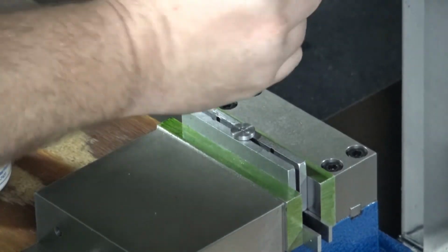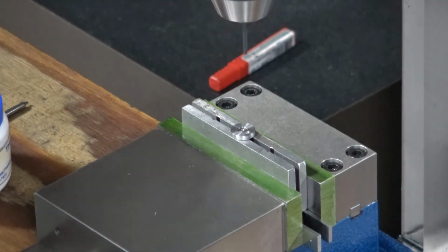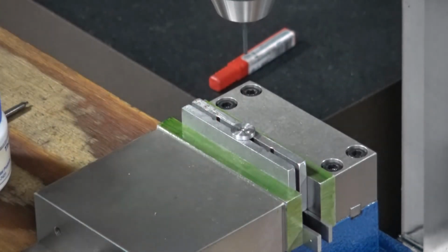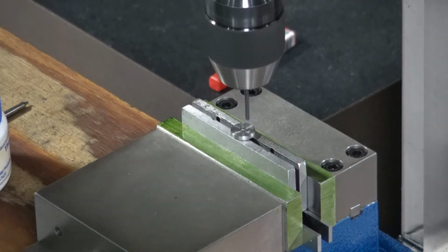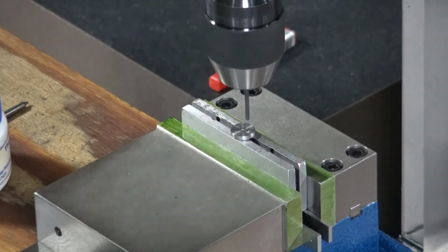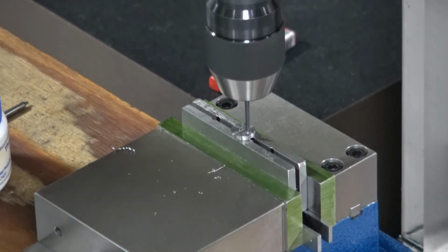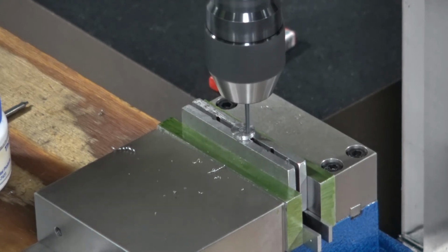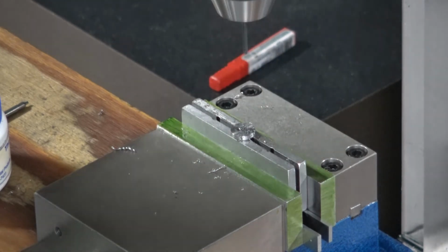Put that drill bit in. Same thing, RPM I've calculated. Spindle forward. We're going to come down. I think I'm going to reposition that quill handle so I can stay out of your way. And now we're going to drill that hole all the way through the workpiece. Okay? See how nice that drills? Drill the hole through. Stop the machine.